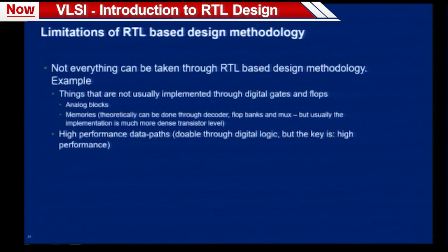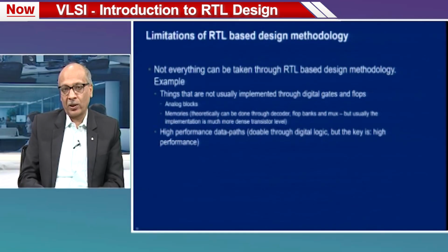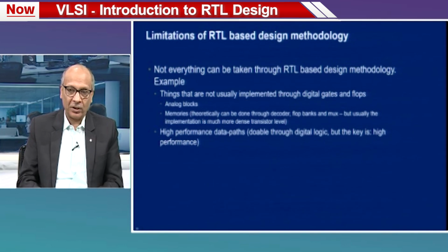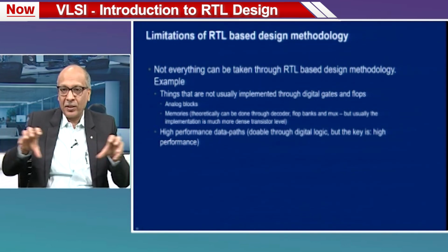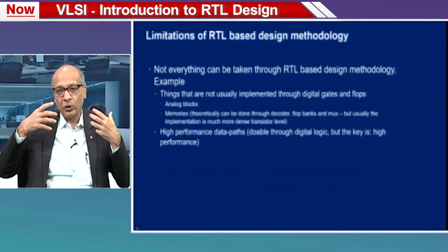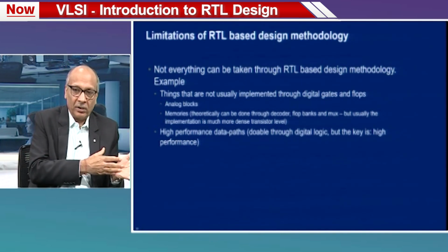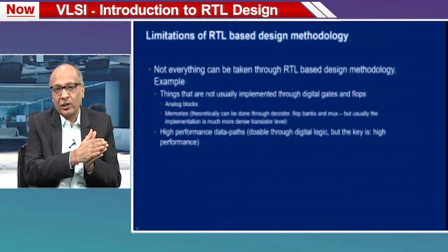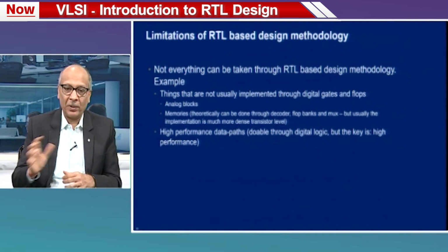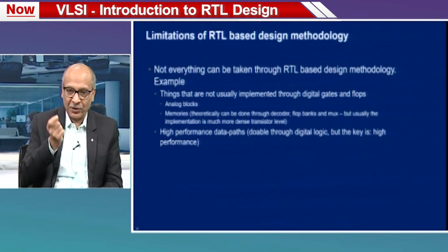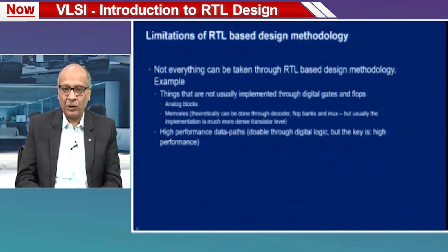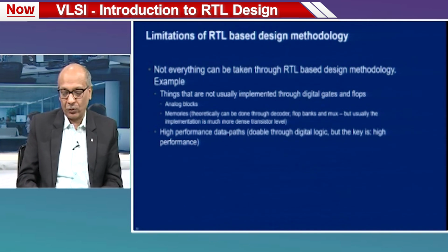So I'm coming back to this slide now. Analog blocks, memories, these are not realized on digital logic. So RTL based methodology does not work for these kind of designs. If there are very high performance data paths, theoretically we can do it through digital logic and hence through RTL, but typically these are done through custom layout, because these are very high performance. People who are very, very experts in these high performance data paths, they will do a custom layout design, each individual transistor being handcrafted and so on.